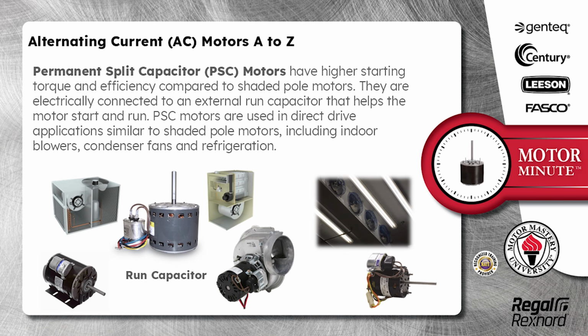Permanent split capacitor PSC motors have higher starting torque and efficiency compared to shaded pole motors. They are electrically connected to an external run capacitor that helps the motor start and run. PSC motors are used in direct drive applications similar to shaded pole motors, including indoor blowers, condenser fans, and refrigeration.